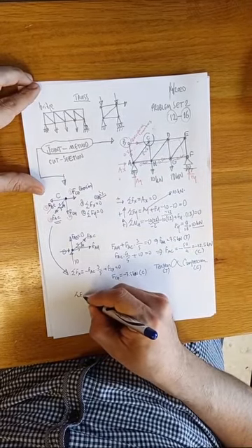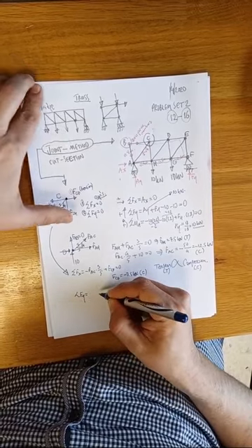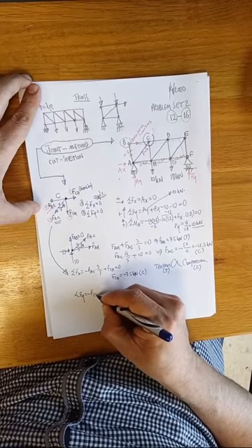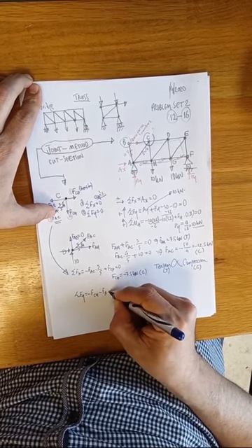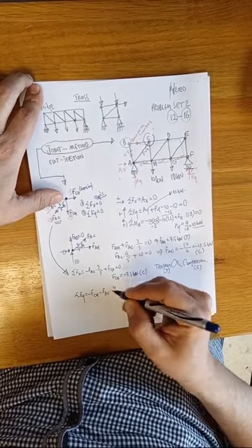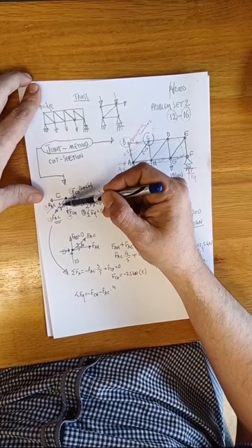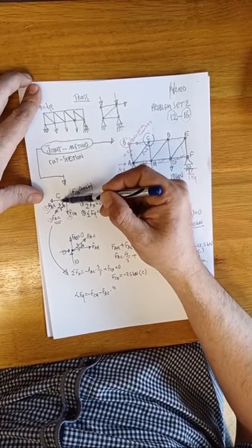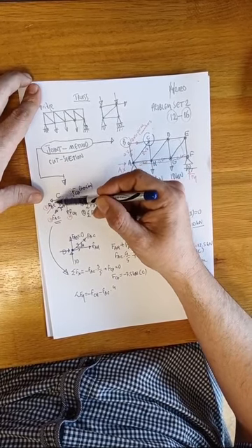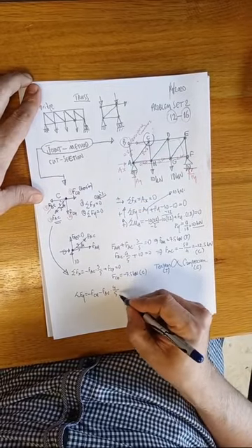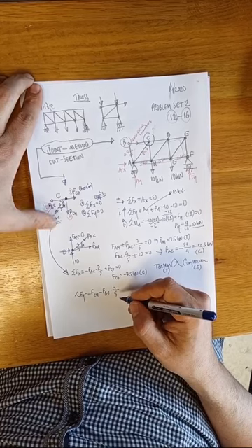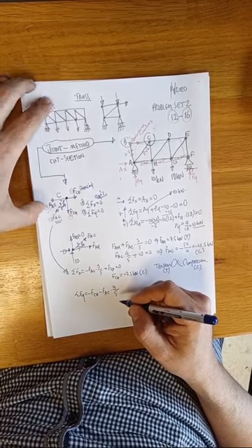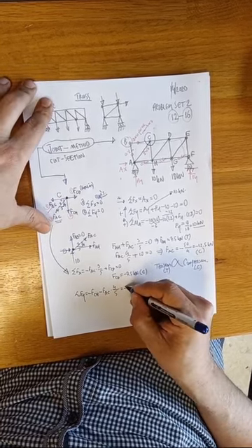To do this, in Y direction the forces are, one of them is minus FCH, the other one is FAC, but FAC's this time what? FAC's sine component. So this is alpha, sine of alpha. What is this? 4 divided by 5 this time, and there is no other vertical force in vertical direction, so this should be 0.